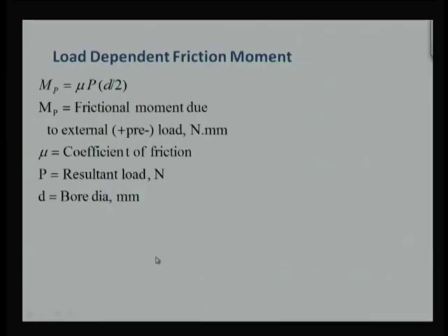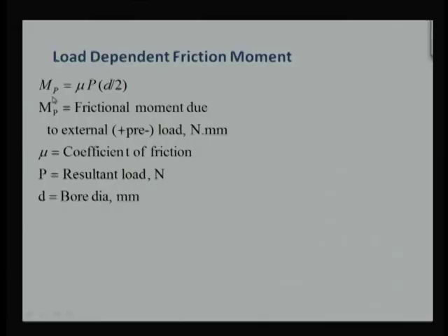Let's take the first component, which is the load dependent friction moment. Again, we are using the friction moment. We are not talking about the friction force, because it's the rolling action, and whenever there is a rolling action, generally we use the word moment instead of the friction force. So we need to calculate the friction moment due to the load component.